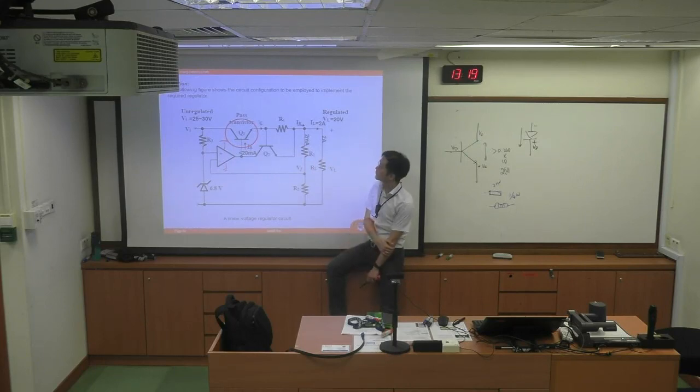For the sampling voltage, it's 1 over 1,000 or less of the load voltage. Is this a general rule? Yeah, I would say this is a rule of thumb. You don't have to follow this way, but I would say it's a good balance between the resistance-induced noise versus the power consumption of the circuit.